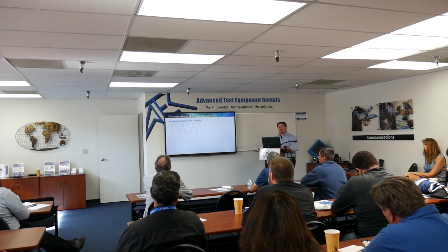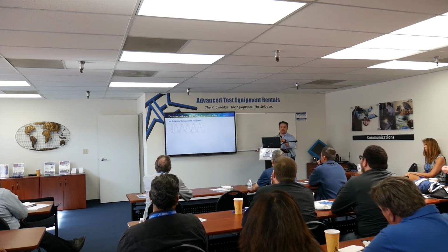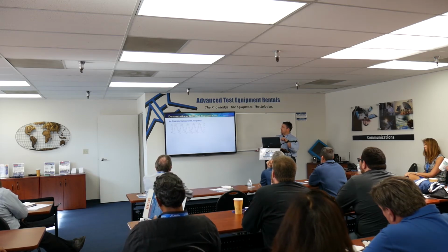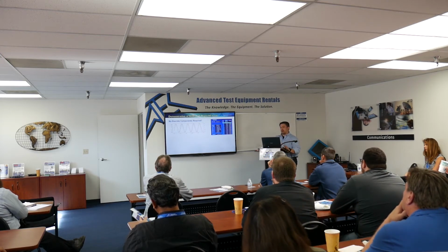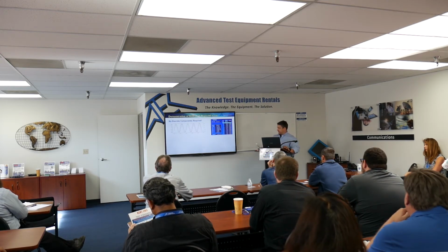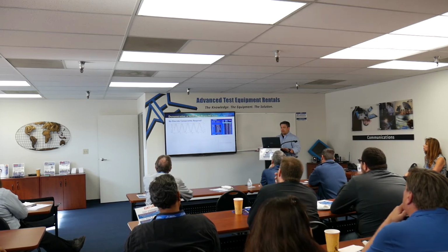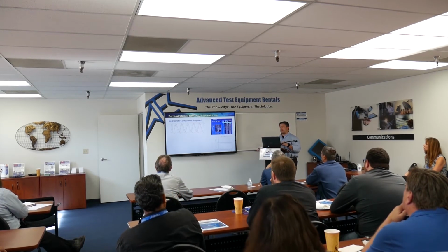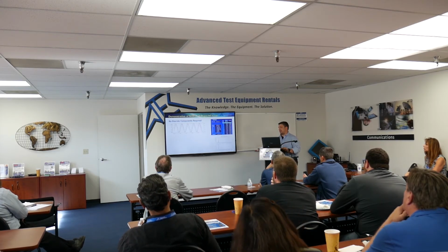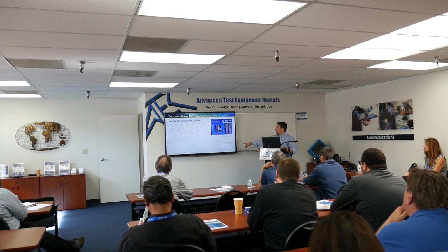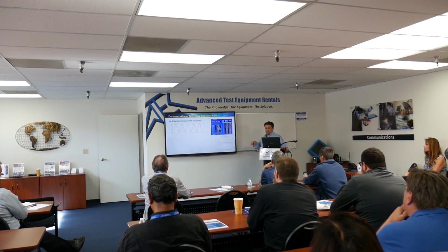So again here, here's a wave shape of actual data collected during testing, I believe this was a 0.75 power factor. And here, this was verified by Yokogawa. This is a WT1800, where you can see 0.75 to verify that. And then also, with the built-in measurement capability of the 9430 and all our other products, we give you access to all that raw data. So another thing you can do, like here for example, I was doing some FFT analysis in Python with it, so I was able to pull that data out as well.